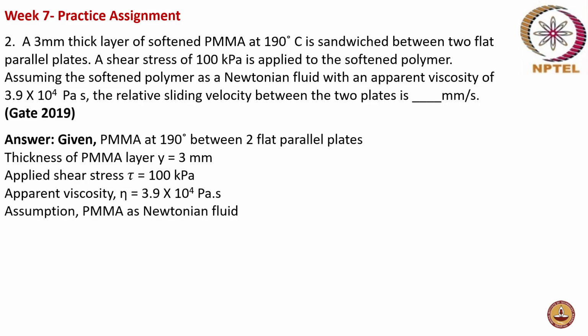Now the assumption is that it is a Newtonian fluid. So what we can apply is Newton's law of viscosity. Newton's law of viscosity says shear stress is equal to apparent viscosity into velocity gradient, right?